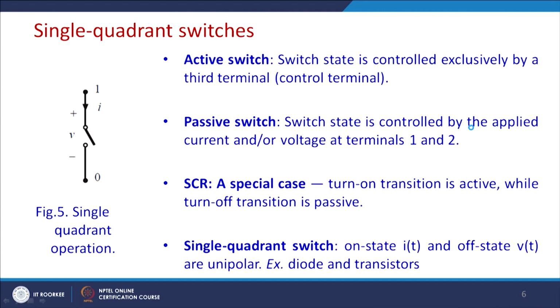Now a problem of the mechanical switch is that it is slow. So for this reason we require semiconductor switches, since semiconductor switches have a depletion layer and junction potential, and inherently carry some amount of blocking potential. For this reason these switches are basically active devices. And what is an active switch? There is a difference between active devices and an active switch. An active switch is one that is controllable. There are devices which are half controllable, and there are devices which are fully controllable.